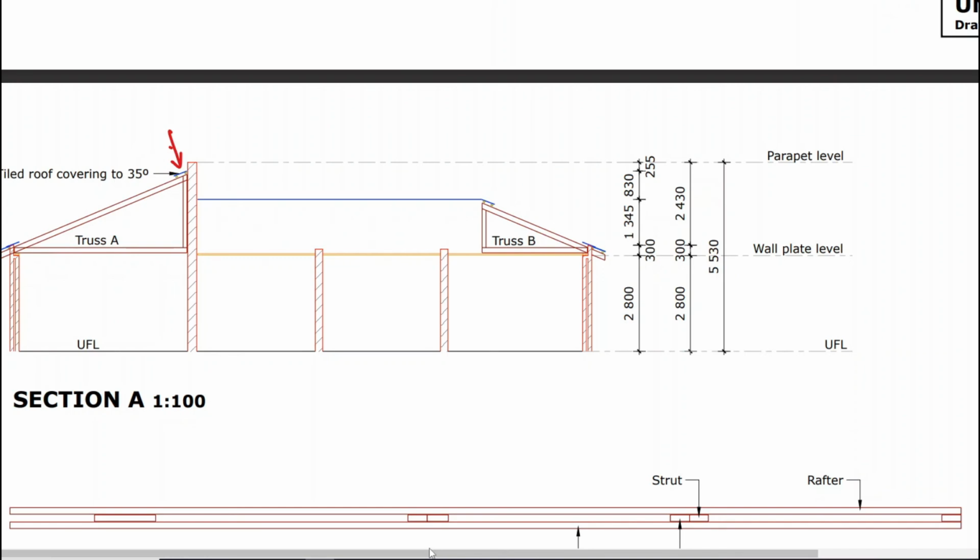If it runs with the slope, sort of along the slope, there's no factor, and this is for obvious reasons. It hasn't changed in altitude or length based on an angle or degree. However, this face does run up a slope, and so it does need a factor of 1 over, since it's 35 degrees, we'll say 1 over cos. 1 over cos 35.